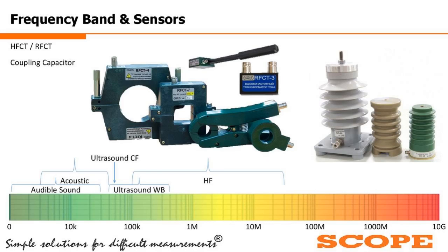As you can see here, a lever is here, a screw is there. You can just take this screw out and it will open. It is a clip-on kind of CT. You can place it around the wire that generally grounds the sheath of the cables. That is quite a common application, or on the earthing plate that grounds the transformer tank. You can place these RFCTs across it without any requirement for shutdowns. They come in various IDs and ODs, so as per your requirement, you can use them.